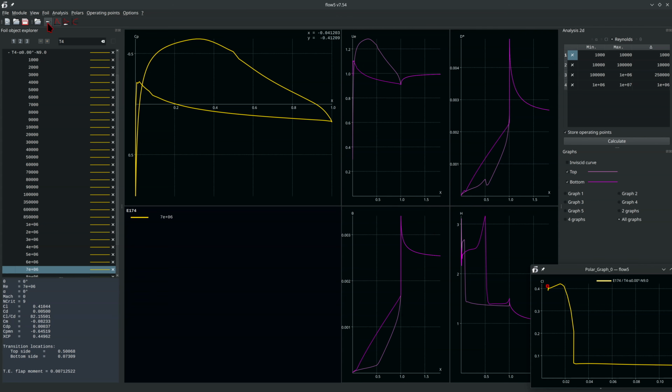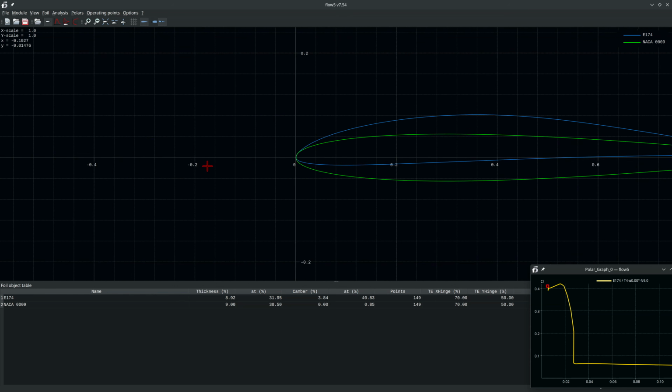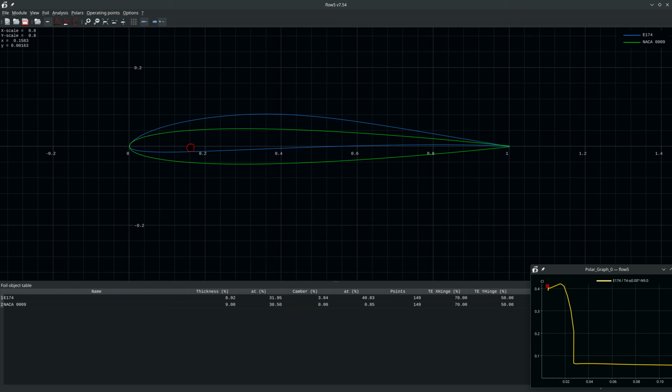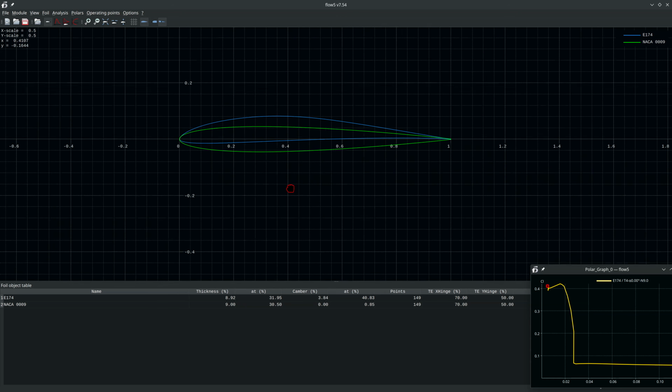Alright, and lastly, the design view. I think we've already talked about that one. Just a few shortcuts that may come in handy. If you double click on a view anywhere in Flow 5, it usually centers on that view. If you are using a laptop without a mouse wheel, you can press the Alt key on your keyboard and move the mouse to zoom in or out.